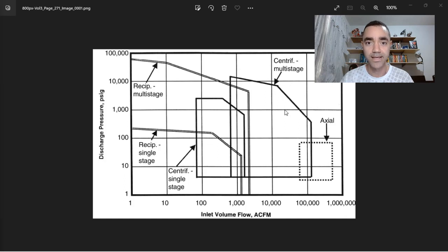And now that you have this point of view, or that you have this information, let's take a look at the 6 items that I shared with my student. So my first tip, considering that the compressor is already installed and in operation, but he is facing problems with the breakdown of the equipment, is to verify if the current operating conditions match the specification datasheet of the compressor. What I mean by that?